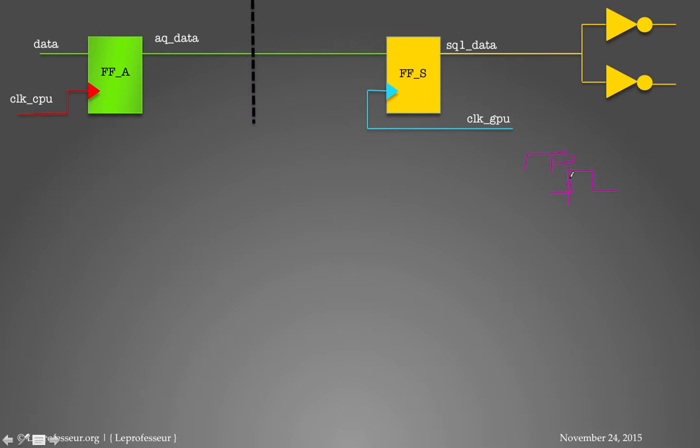So this is the rising edge, and the data signal should be stable. This window is the setup window. The signal also should be stable after the rising edge of the clock for a certain time, depending upon the technology requirement, and we call it hold time. Separately, these are called the setup window and hold window.